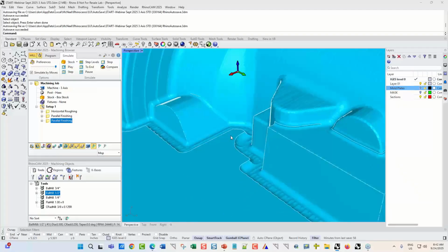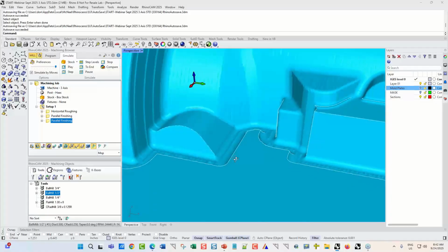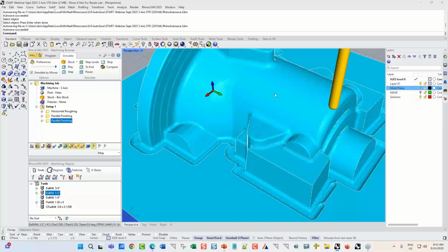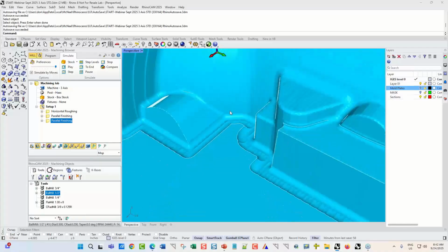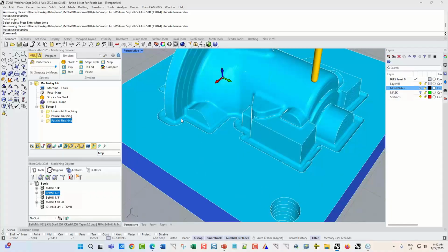These light colors here, those are just the simulation silhouette colors that we had turned on. This is not a gouge or anything. So as you see, we've got a finishing pass on the contoured areas of the part, and we have a 1/4 inch radius down here. And again, this is extra stock that we're leaving there until the end. So we have a 1/4 inch bitangent radius right now at the bottom, all the way around.